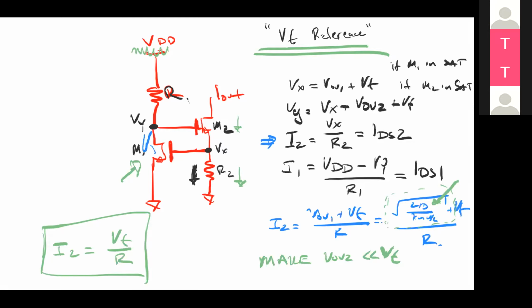However, with a band gap, you have additional complexity in designing the rest of the circuit. So if you were designing a simple circuit and just trying to get a mostly supply-independent current, I think this is a reasonable choice. Does that answer your question at least somewhat? Yes, I'm just thinking if there is anything else. Yeah, it does.